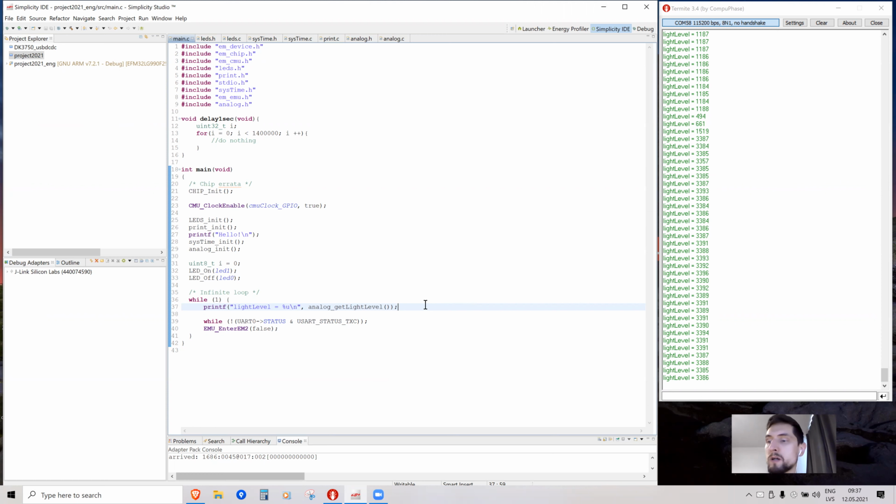And if you cool it down, it decreases and resistance increases. So many of these microcontrollers have some temperature sensor inside with which you can either measure the core temperature, or if the microcontroller is sleeping a lot, after you wake the microcontroller up, if you quickly measure the temperature, then it's basically the temperature of the ambient air. So you can use it like a small, not very precise, but functional temperature sensor.